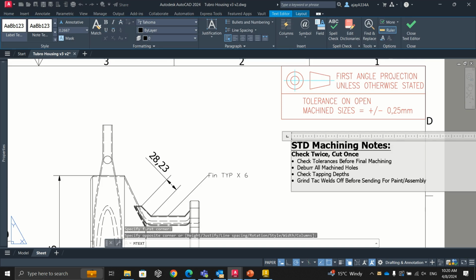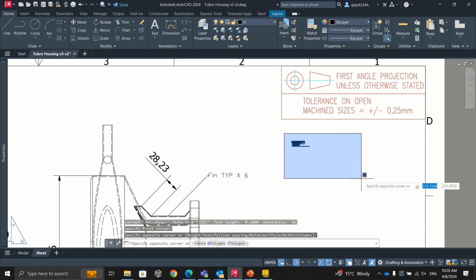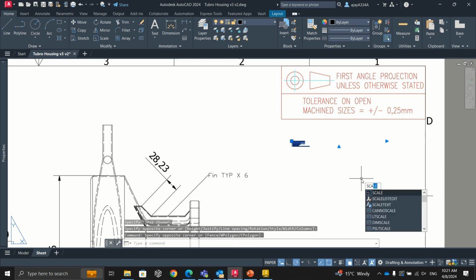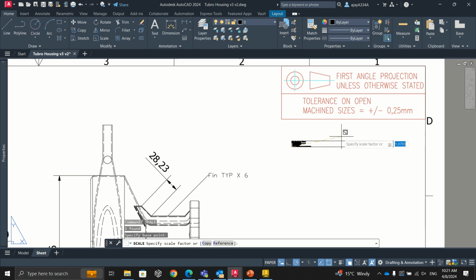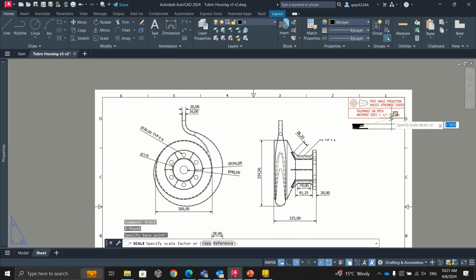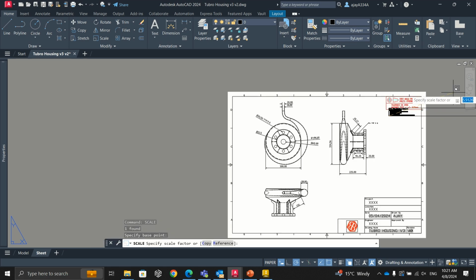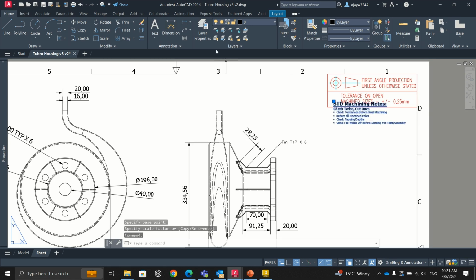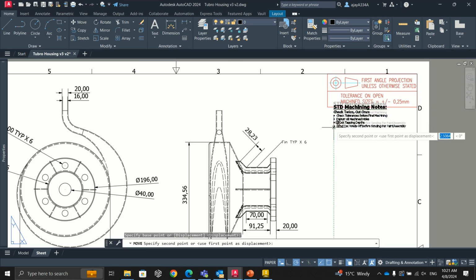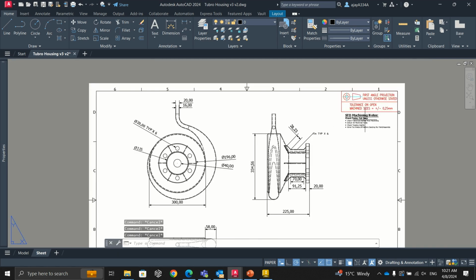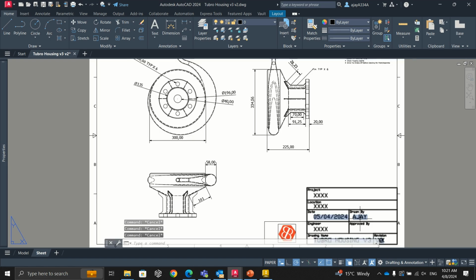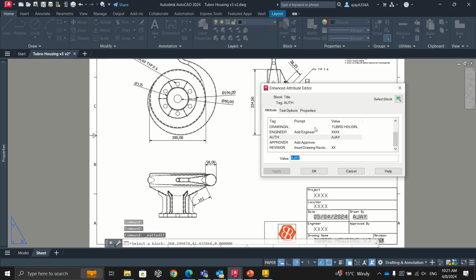Now, machining notes will be added, one by one, individually, in an individual process, unless every single one of your processes is exactly identical. Now, do you want to have a rough surface finish? Do you want to have a smooth surface finish? Do you want to have a specific type of finish? What type of welding are you doing? What type of fastening are you doing? All of those fastener types, any and all notes that need to be sent to your manufacturing team and to anybody else that needs to know what the manufacturing of this product entails, as well as the fitment thereof.